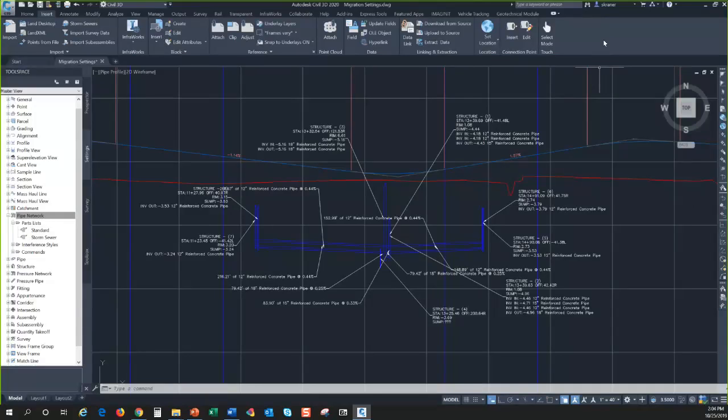And then I took those polylines and created catchments from that. And then I just pulled information out from that and then plugged it in manually. There's not a link to take catchment information into storm sewers. The catchment information doesn't go directly in. That's got to be plugged in that dialog box where I plug the information in.